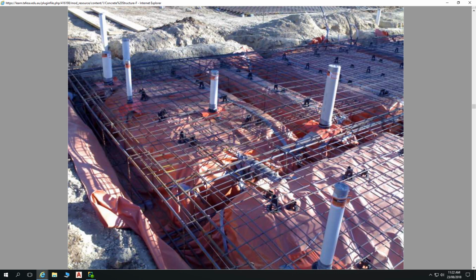Also, at this stage, we can look at a slab. Typically, even if we don't know that building project at all, we can go, oh yeah, there's a bathroom happening there. They're having a separate vanity. This is our laundry, etc. So we look at the size of pipes and go, okay, 100 mil pipe here, that's got to be the toilet. Floor trap. That's going to be the inspection for that plumbing run outside of the building. That 40 or 50 mil is for our vanity. Not exactly sure which one of these is which, but it might be laundry or so.